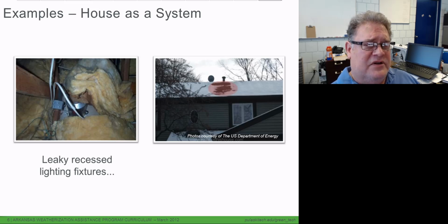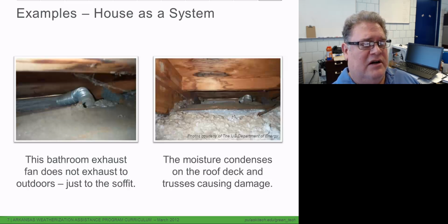Now here in Arkansas, we don't see a bunch of snow in central Arkansas, but we see enough that everybody here knows what an icicle looks like. However, ice dams are kind of rare for us, but a little bit further north, ice dams are quite common. An ice dam is when we have premature snow melt and the water moves down to the edge of the roof, which is called the eave, and the air temperature is still below freezing. That eave is going to be below freezing. So we have heat leaking out of the house, melting the snow. The melted snow or water moves out to the edge of the eave and refreezes, where it will create pretty little icicles, but it'll also create these mean little things called ice dams. And water will pool or puddle behind it. That's going to get under the shingles and ruin the roof deck and the sheetrock inside.